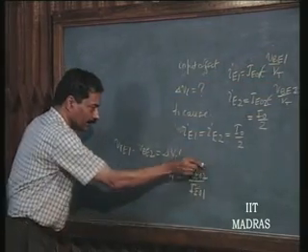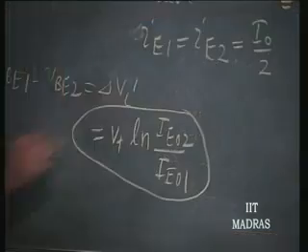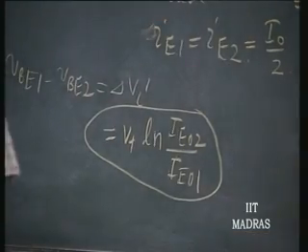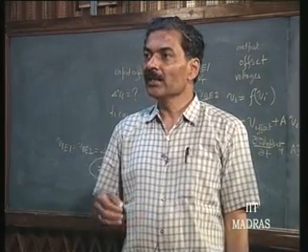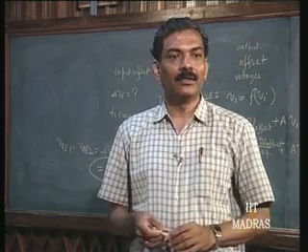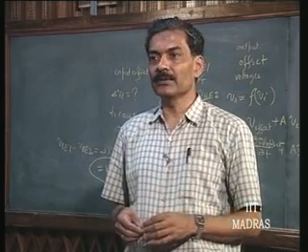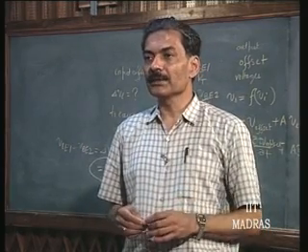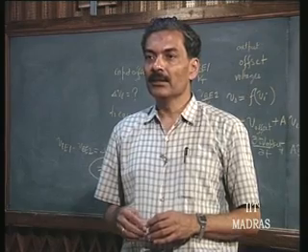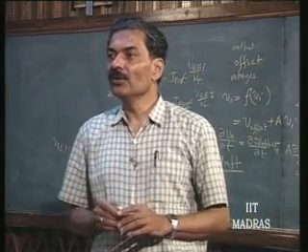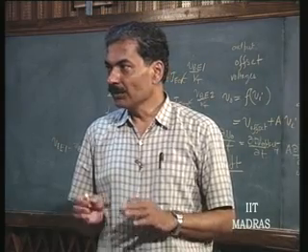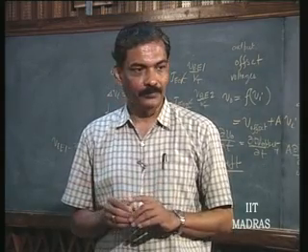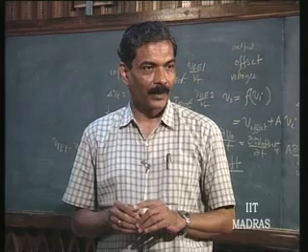So this is defined by the manufacturer as the input offset, because only the manufacturer has to tell you what it is. It depends upon the transistor mismatch. Typically for the technology that exists today, for the bipolar transistor, this is ranging between 1 to 2 millivolts. Is this clear?